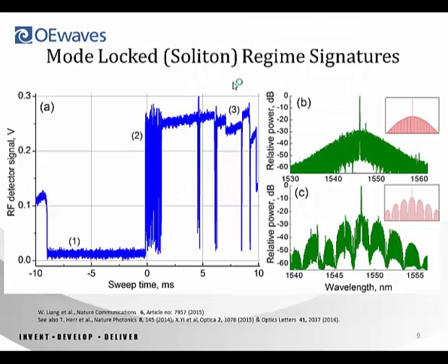Those oscillators, though, don't use the mode-locked regime of frequency combs. And as I'll show in the next couple of slides, the mode-locked regime is the best one to generate spectrally pure signals at low offset frequencies. So this is how a mode-locked comb spectrum looks. The green lines here show a couple of envelopes of frequency combs in a microresonator, as seen at the output. The top figure shows basically the spectrum of a single soliton traveling within the cavity, and we can say single soliton by numerical simulation, since we didn't make an optical observation. And the bottom figure, the green line, shows a couple of solitons generated in the same cavity.